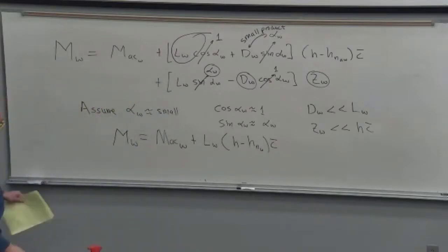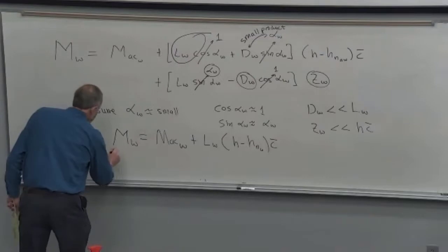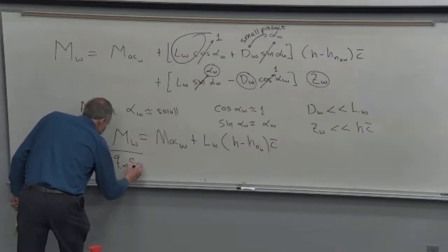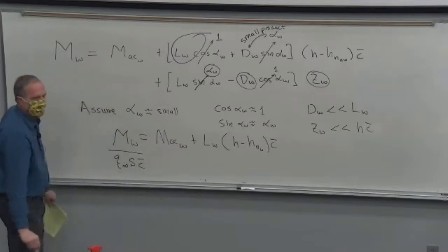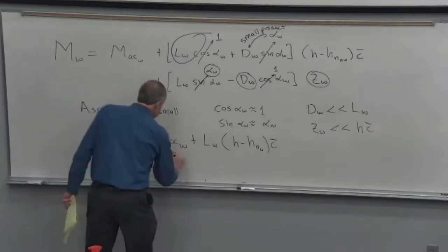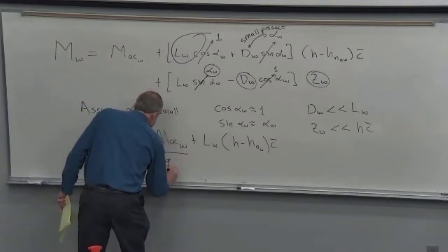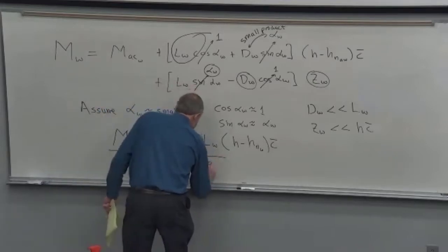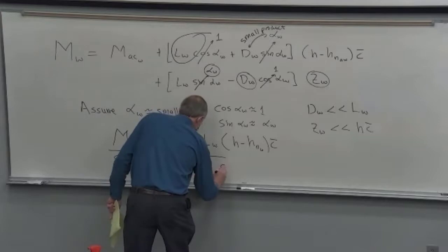And then in aerodynamics, we like to deal with lift coefficient, drag coefficient, pitching moment coefficient. So we divide by Q infinity S C bar to non-dimensionalize. And we just define the coefficients in terms of these things.